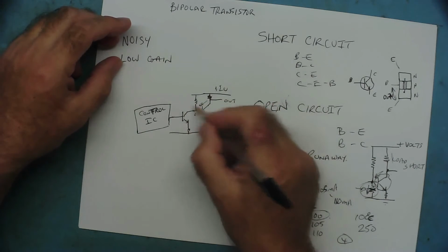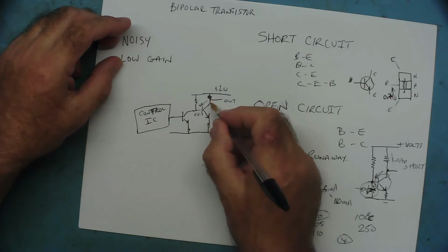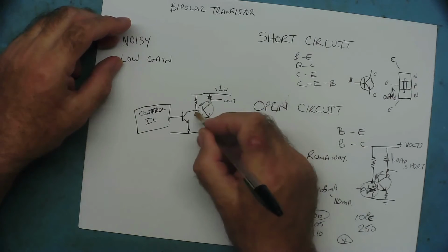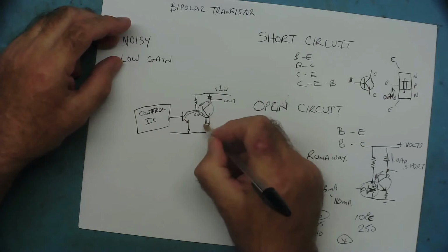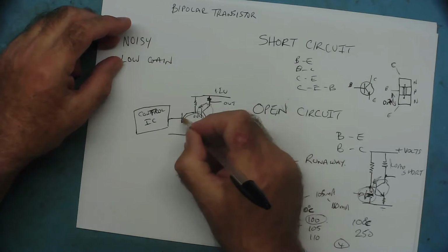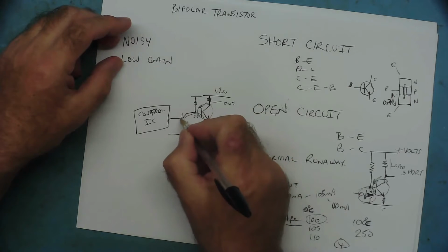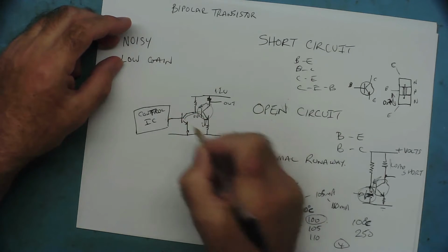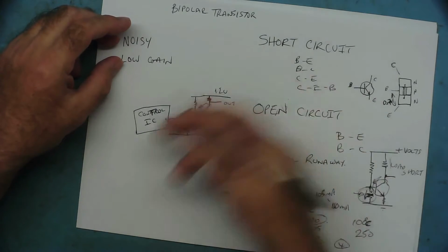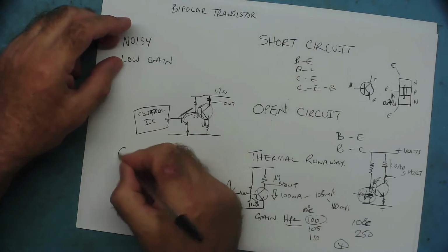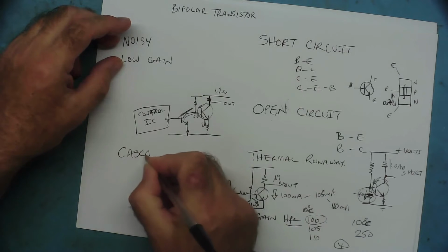And depending on the configuration of the circuit, this one going short circuit can cause this one to go short circuit. This might now be pushing too much current that way because that's all short, and this one blows short circuit. And then this one can now, because it's short circuit here, there's 12 volts coming down to your control IC, and that can go short circuit. So this is what I call a cascade failure.